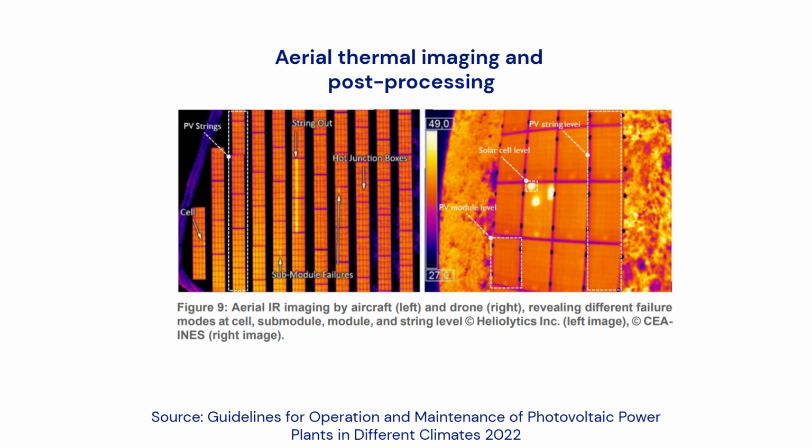Leading providers of aerial PV inspections benefit from having access to very large and steadily growing inspection portfolios, already reaching the gigawatt scale. This allows them to compare underperformance issues and anomalies across many PV plants, using extensive fault libraries together with proprietary image analysis and IR and RGB mapping software. As a result, these services can detect a wide range of problems, from large-scale string, combiner, or array outages to more localized issues at the module, submodule, or even cell level. These include subtle defects such as potential-induced degradation, electrical mismatches, and associated hot spots.